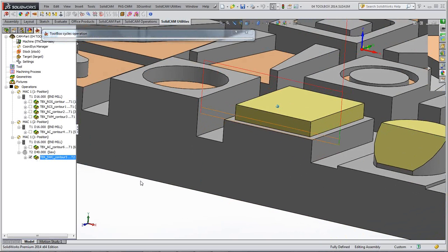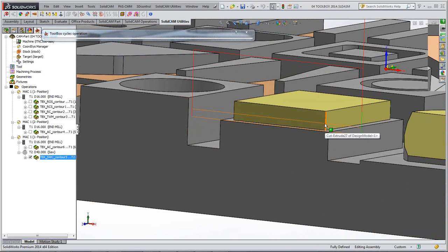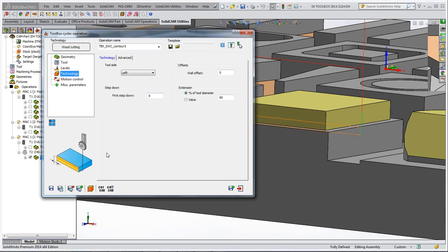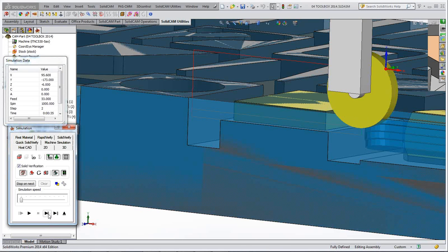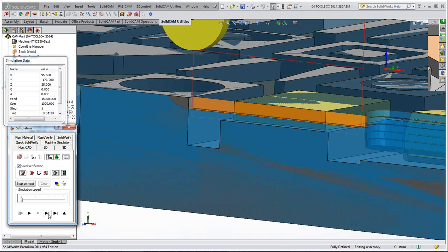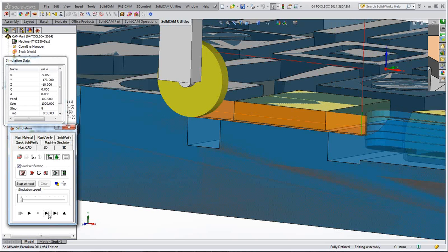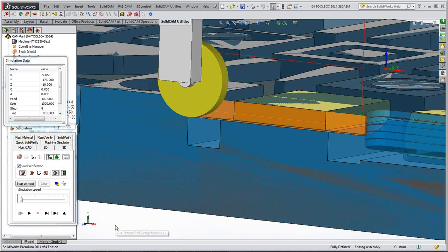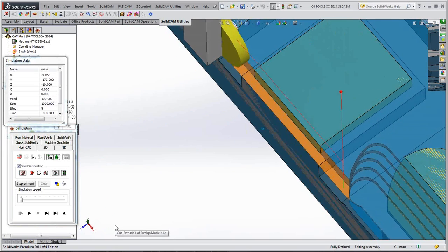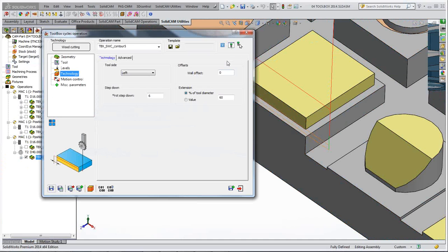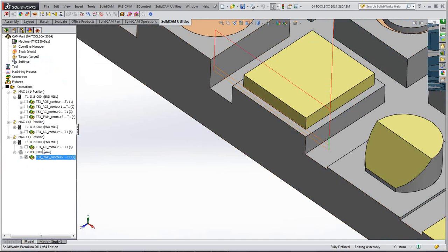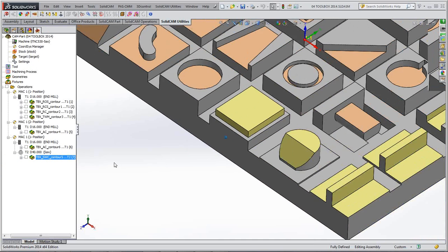There we have two lines there. First one 6mm down, second one at the finished depth, and I can quickly simulate that for you, and you can see what that looks like. So the tool comes down, goes down to 6mm, zing, off it goes, back up, down again, and across. So that's our piece of wood cut off as you'd want it. Okay, that's a quick and easy toolbox cycle there that helps the chaps in woodworking.